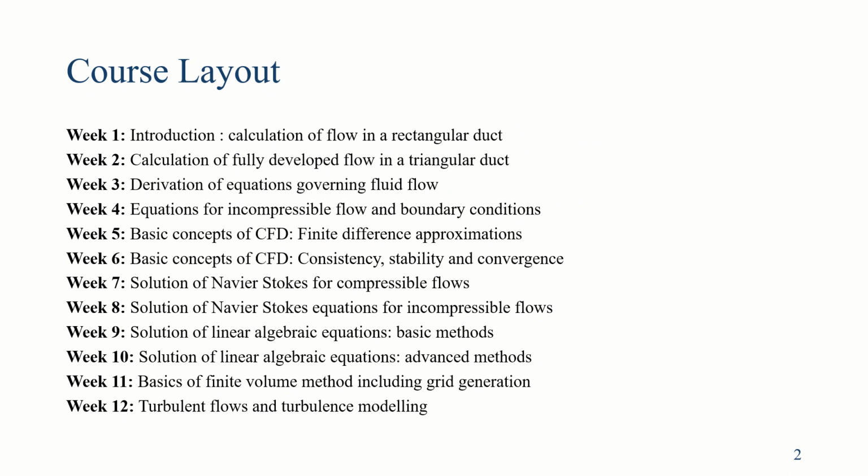For example, we say that we are getting a parabolic profile in the pipe flow problem, but in doing that experimentally we cannot observe when it is approaching that parabolic profile. We can observe that from computational fluid dynamics, where we can say that it is transitioning from the flow, and it is attaining a fully developed flow at this particular second. So we can see the time evolution of flow also.